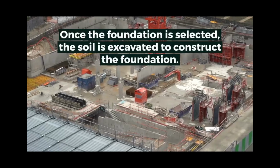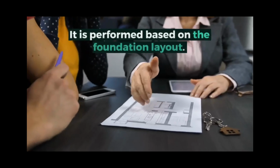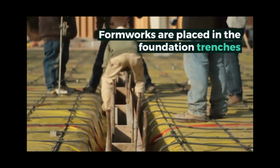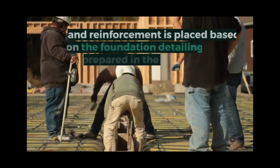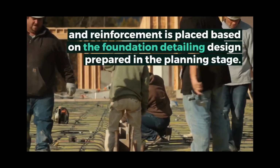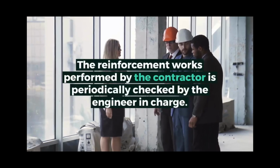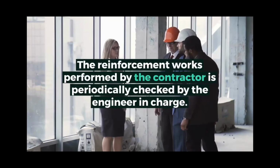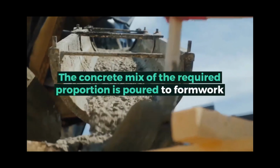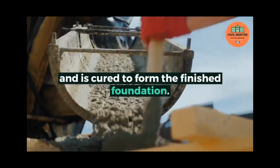Once the foundation is selected, the soil is excavated to construct the foundation. It is performed based on the foundation layout. Formworks are placed in the foundation trenches, and reinforcement is placed based on the foundation detailing design prepared in the planning stage. The reinforcement works performed by the contractor is periodically checked by the engineer in charge. The concrete mix of the required proportion is poured into the formwork and is cured to form the finished foundation.